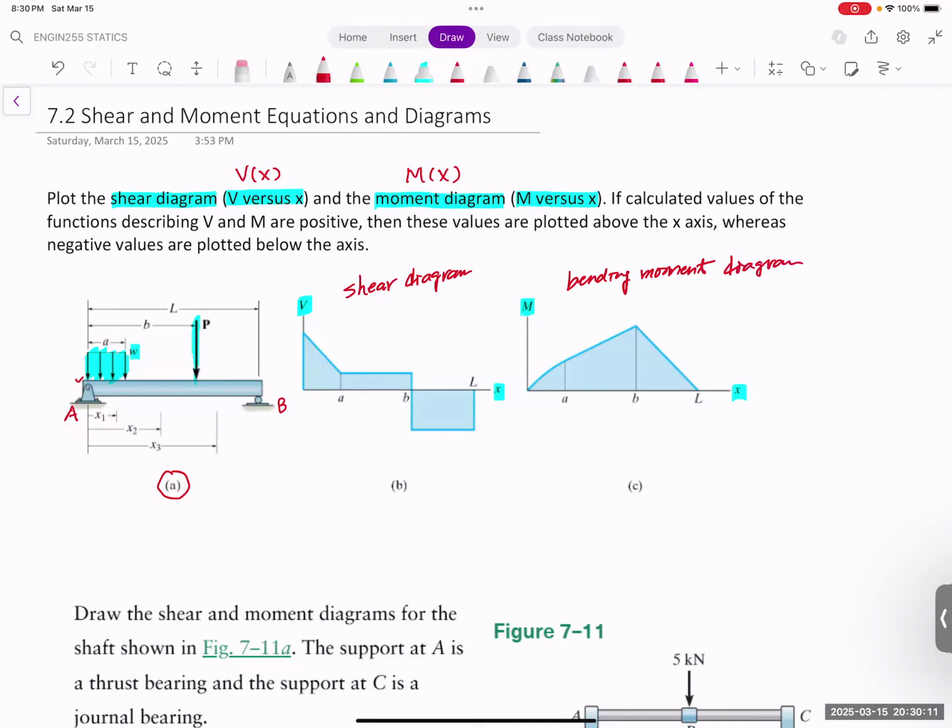What we really care about is that if you have this diagram, I can clearly identify where the most loading is applied to this member. Let's say, for example, if you look at the shear force diagram, you can see this is the maximum value. This is the minimum value. The maximum value tells me how much load the member has to support. So when you design this member, you will select the property and the material that can support this kind of load.